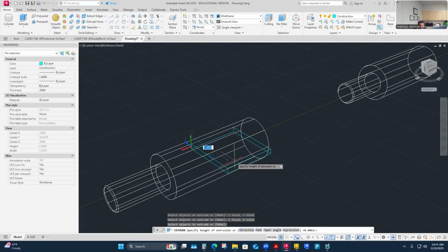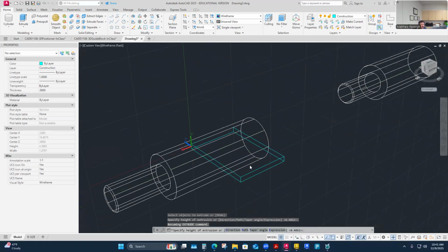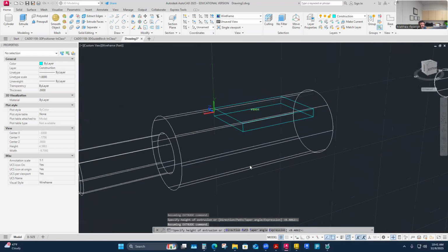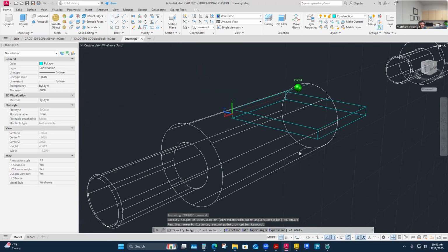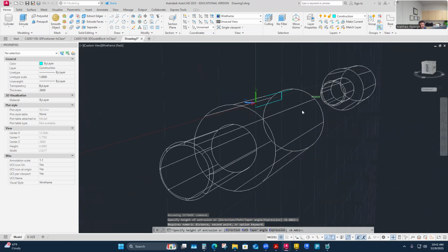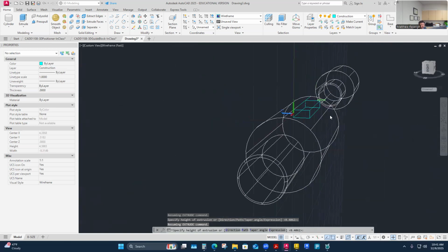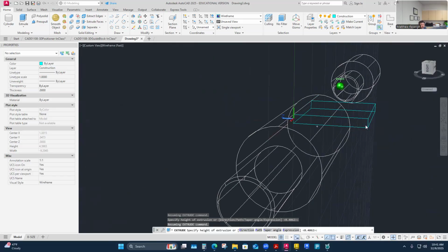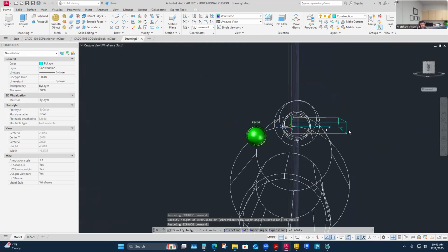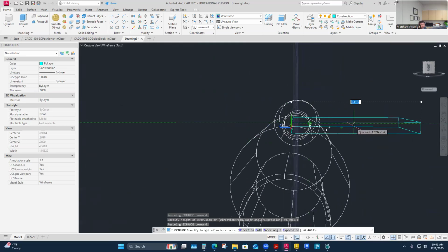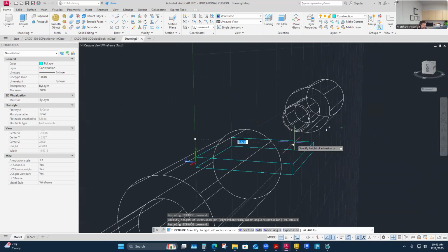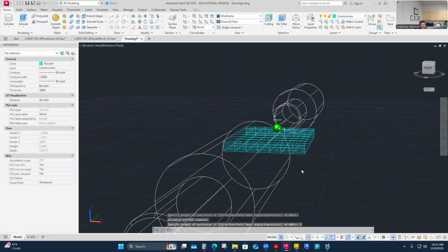Yeah. I'm doing an extrude on mine, actually. My press pull is acting a little bit funny, so I went over to my extrude and I chose my geometry. And now this is allowing me to, so this is kind of what I was hoping to see, but I'm able to pull this extrusion across. And for this one, I'm just going to pick any dimension that's complete and passed here. I just want it to cut through. So maybe I'll just say it's a 1 inch extrusion. Yeah, there's a 1 inch extrusion.